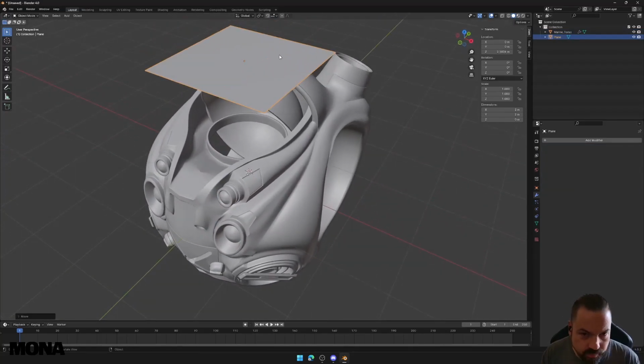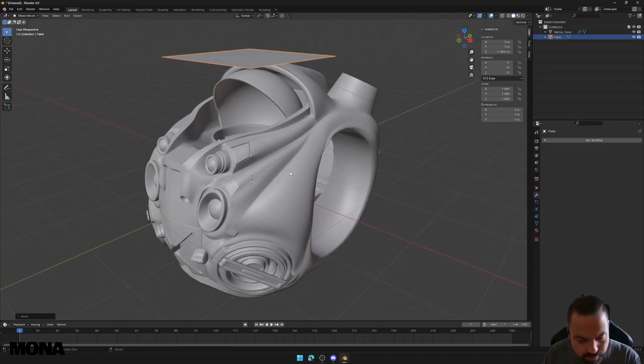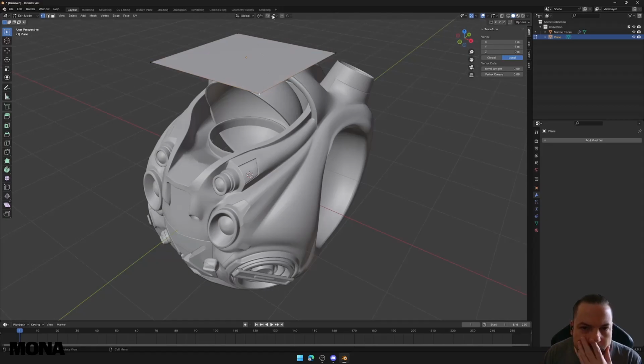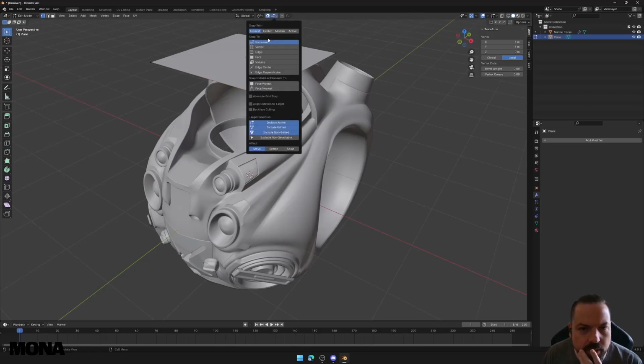So what we want to do is make a low polygon asset with our little plane on our high polygon asset. And then we can bake that information or texture that information in different ways. So I'm going to edit this. Now the one tool you want to use is Snap. I'm going to turn that on up here and then go down to Face. Yep.